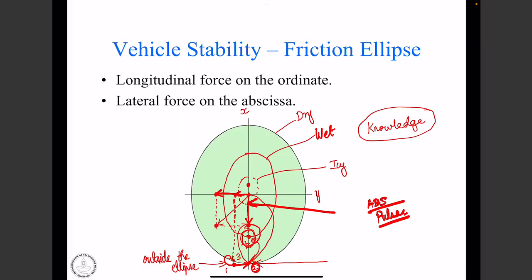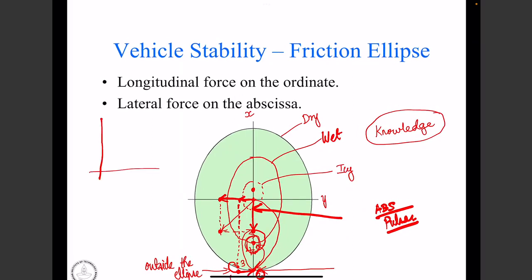See, what do I mean by that? Let's say you slam the brake. The deceleration profile will be different, right? So you plot A versus T. Let us say this is gradual braking, as opposed to slamming the brake. The final deceleration may be the same, but the deceleration profile is different. So consequently, the dynamic load transfer profile will be different.